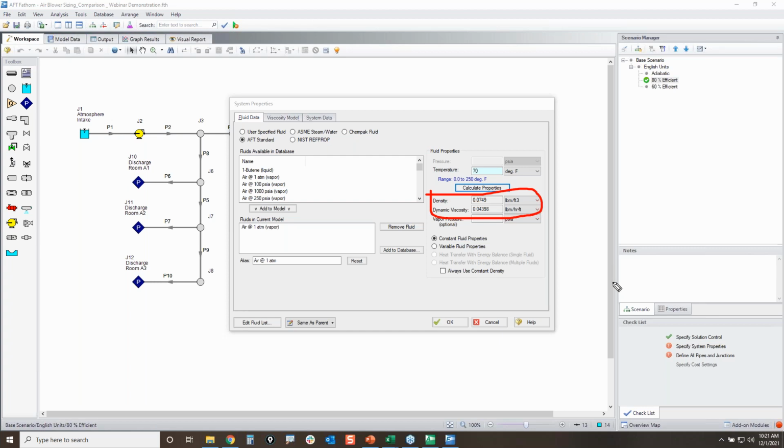And that is where the incompressible flow methods can start to break down, because in reality, all those thermodynamic parameters are changing. Sometimes they may be significantly different when you're assuming incompressible flow. Sometimes they may not be. It's very much a case-by-case basis.